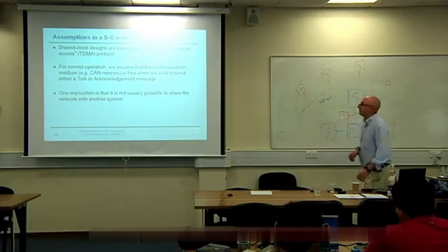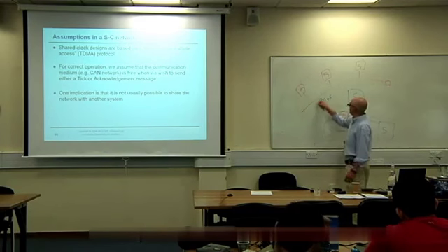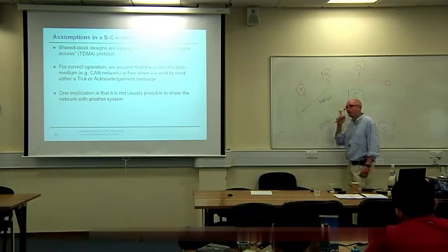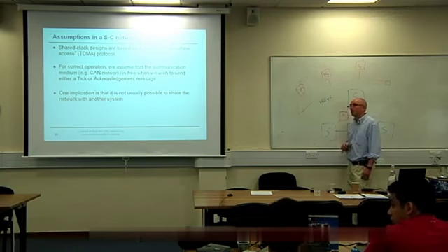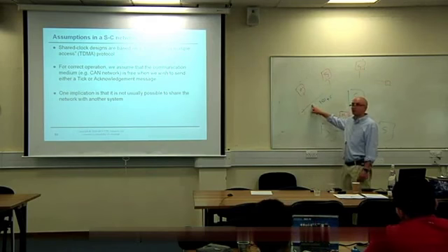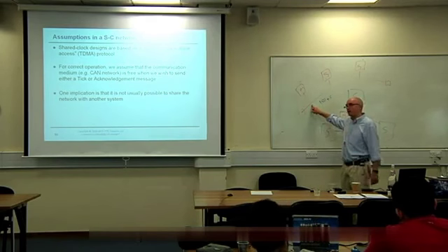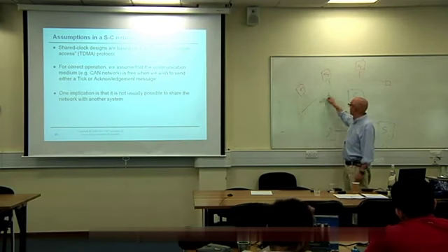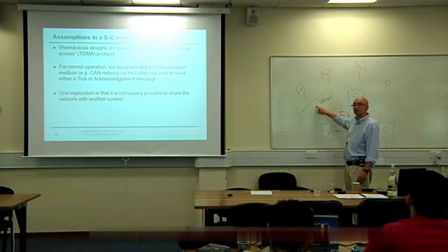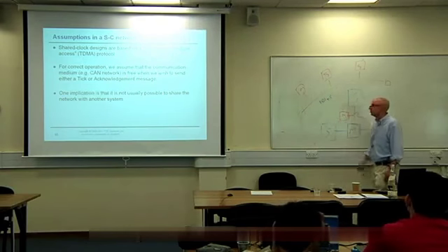If it didn't get it in time. So I want to talk from here to here. Only one person can talk at a time on the bus, and there's no message preemption on a bus. Something else might be talking already. So if somebody else is talking, at best, and there are message priority levels in here as well, at best, if somebody else is talking and I try and send a tick message, that tick's 150 microseconds late.